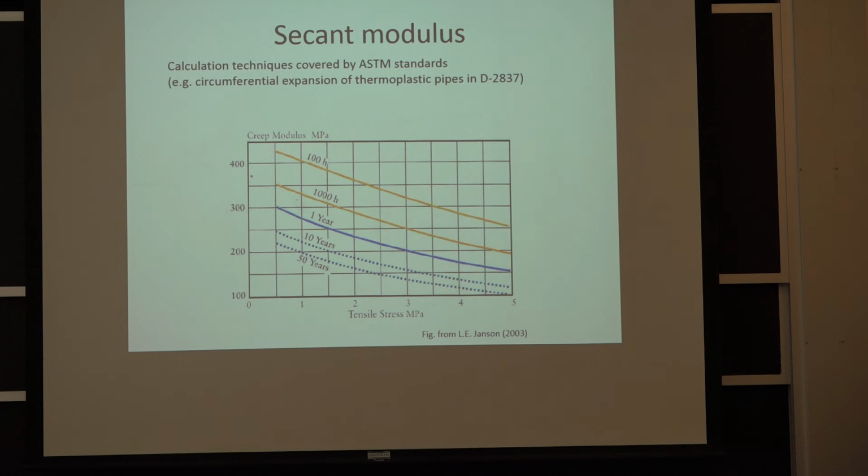Okay, well, good luck to you, because the minimum, I would say, is a 4-month test. And even there, you will be benchmarking against other materials of a similar nature that have been tested 4 months, but also been in service for 20 years, to know whether or not there's this special phenomenon that changes over time, even chemical degradation, UV. There's a lot of things that can happen over time. So we really here are just focusing on the basic stuff. And there are a lot of standards on how to do this.